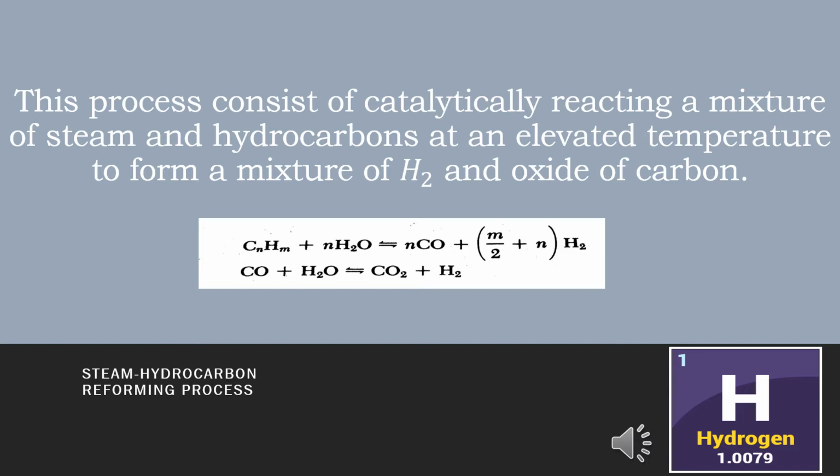A single stage converts 80 to 95% of the residual CO to CO2 and hydrogen. Because the reaction is exothermic, the reactor temperature rises. This enhances the reaction rate but has an adverse effect on the equilibrium.